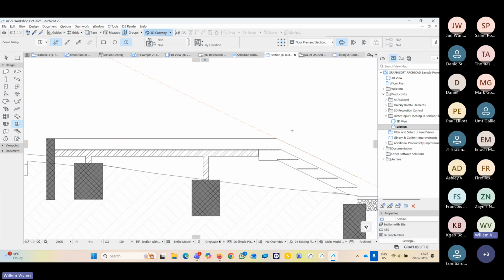And the same, I might want to do the same here, but maybe for recessed lighting that I might want to put in to the wall here. So instead of putting an infinite hole, I'd like to have just a recess. Obviously the depth I can specify.